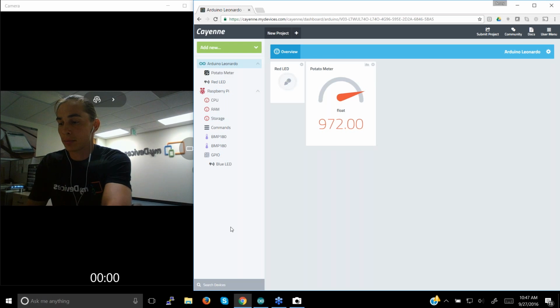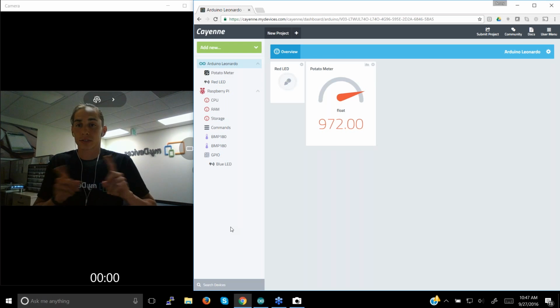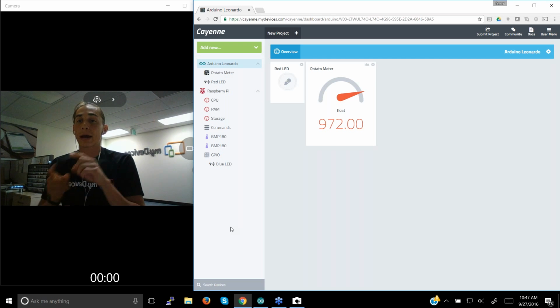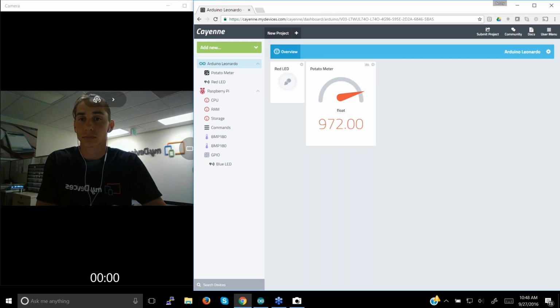Perfect. Yeah. So I'm actually going to do a cross-device trigger. What's really cool about Cayenne is you can think of it as the hub for all of your devices. So when you're adding a Pi, an Arduino, an ESP8266, once we open up the API, you can add pretty much any device you want. Once we get BeagleBone in there, you can make all of these devices talk to each other. So that's what we'll do right now. We'll do a simple trigger: if the temperature on the Raspberry Pi increases, we'll turn on the LED on our Arduino.